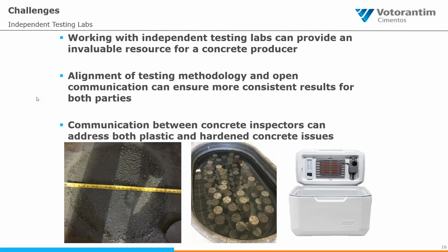On one of the last projects I showed you, we had numerous incidents where the customer would get either a low compressive strength or a low modulus of elasticity, and we would go to the lab to review the results, just to do a quick audit. They were putting cylinders out and not storing them in any sort of controlled fashion. They would be found out on the street. They were not water cured. They were not temperature controlled or anything like that. And the cylinders actually self-desiccated to the point where they caused fractures within the cylinder. So they were getting both low strength results and low modulus of elasticity.